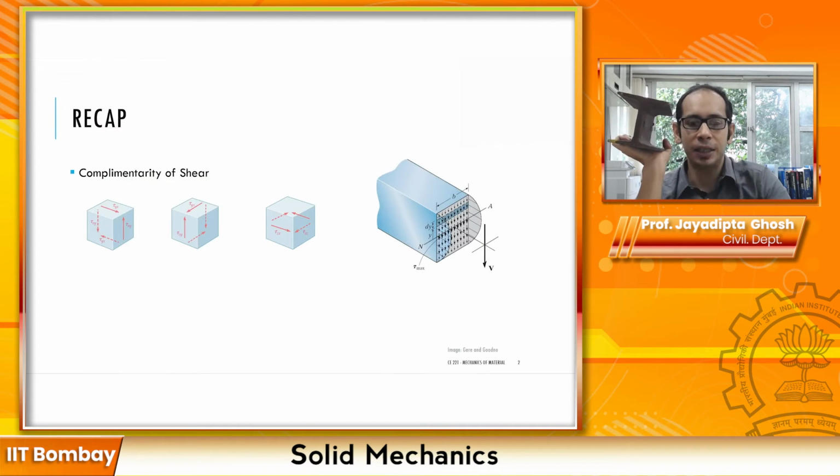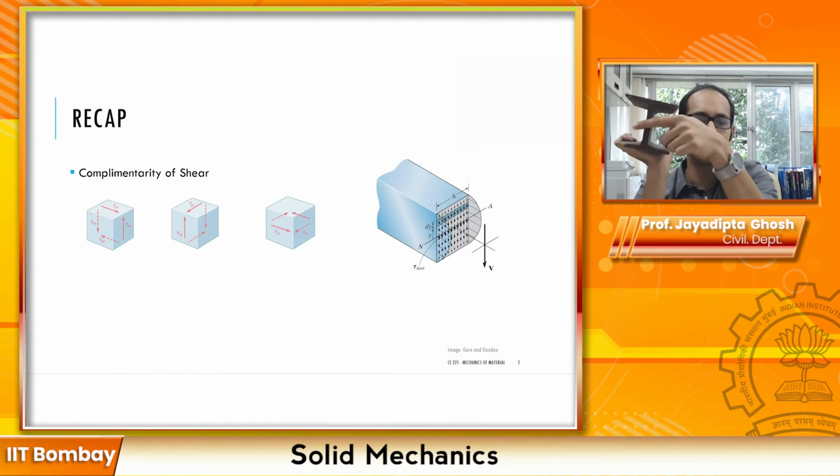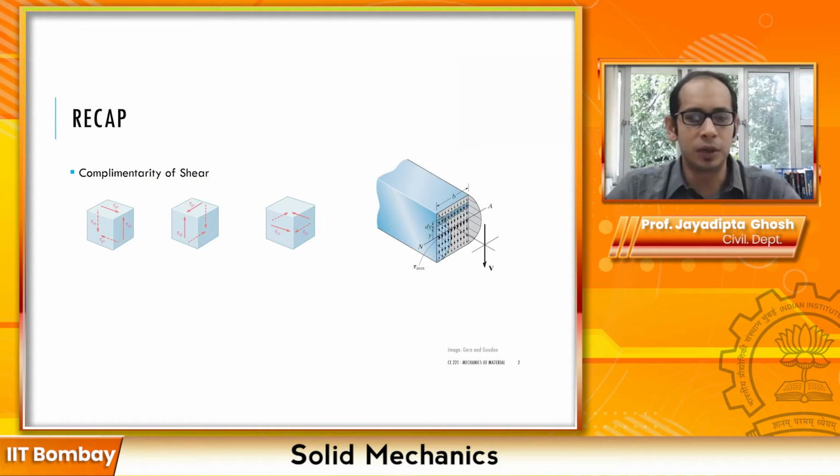So you see that this complementarity of shear will play a critical role. So just keep in mind what we discussed. Since the shear here is 0, this shear will more or less be 0, this vertical component. Since here the shear is 0, this horizontal component for the web part will be 0. So this is the top, this is the flange, and this is the web, and this is the flange again. We'll write it out to have the terminologies particularly clear as well.